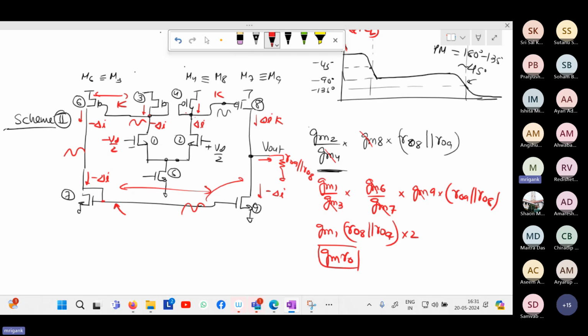You have to increase both W and L. If you increase both W and L of 8 while keeping K unity, so the mirroring ratio remains same, but you are increasing both W and L, then the mirroring ratio is same, K is remaining same, but on your output side, once again, what is happening? If you keep W and L both large, what will happen? Bias current, DC current at the output stage, is it increasing? Decreasing? What is happening? Yes, quickly.